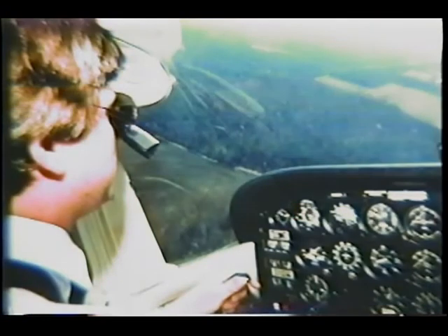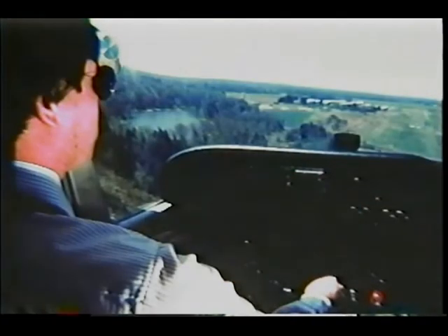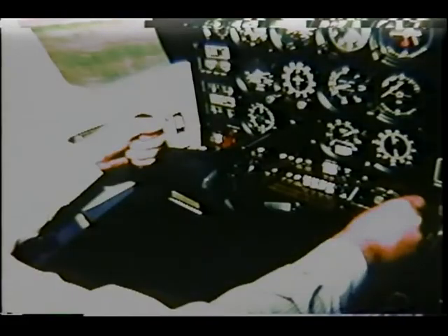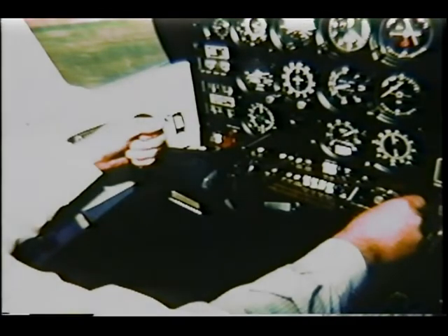I'd like to point out that what you're actually doing here, of course, is taking the first steps toward a possible go-around before setting up your initial approach. And that's a good thing to do. Now that you're both mentally and physically prepared, you continue your initial approach with your hand on the throttle, knowing that you're ready to go around if you need to. And if you do, don't hesitate. Do it. Apply full power and adjust the airplane's pitch attitude.